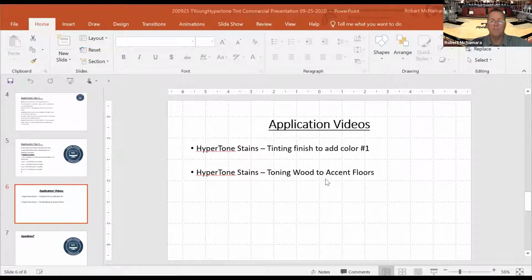It's just much harder to put on with a roller than it is with a T-bar or a paint pad. It's just not recommended at this time, and we just really want you guys to put it on with a pad or a T-bar. And I'll be frank with you guys and girls. If you were to try and do a small room with a pad, it's a little bit of a learning curve, but once you get the hang of it, it works really well.